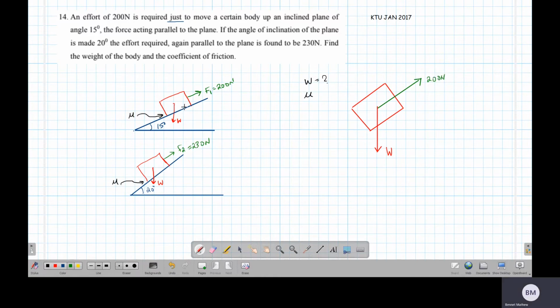Then there is a contact here. This contact will act a force on the body, and the body will also act a force on the contact, equal and opposite. So I will draw the forces coming on the body. I have to draw this contact force, which I will call N1. This is the contact force, or normal force.